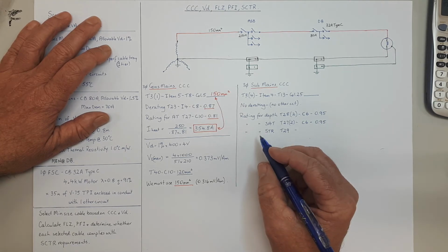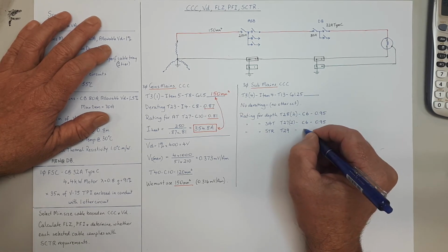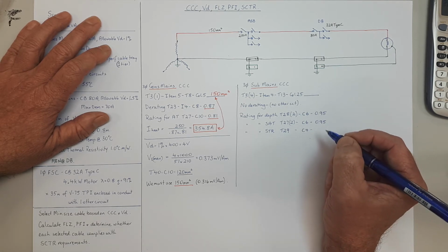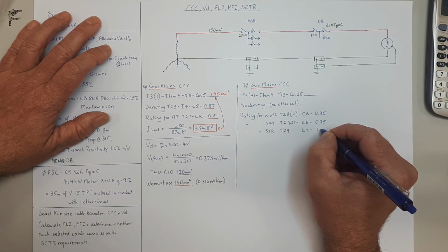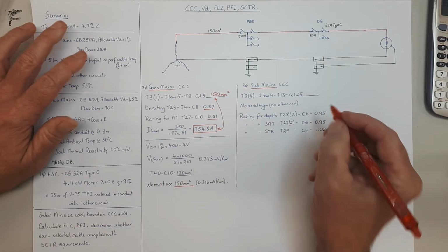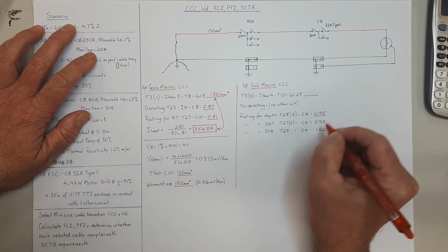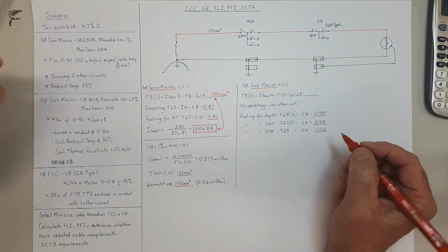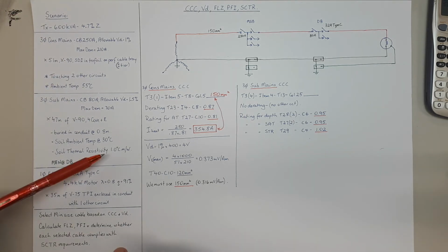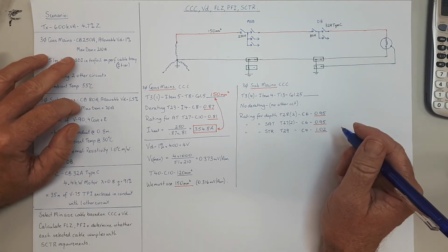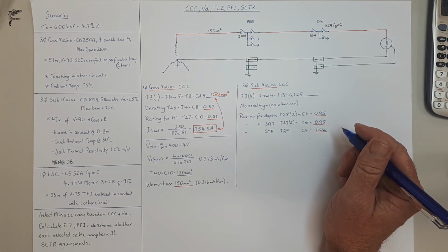And soil thermal resistivity, column 4, it's actually above 1 in this case, 1.02. So there our rating factors, because it turns out a soil thermal resistivity of 1 uprates our cable a little bit.